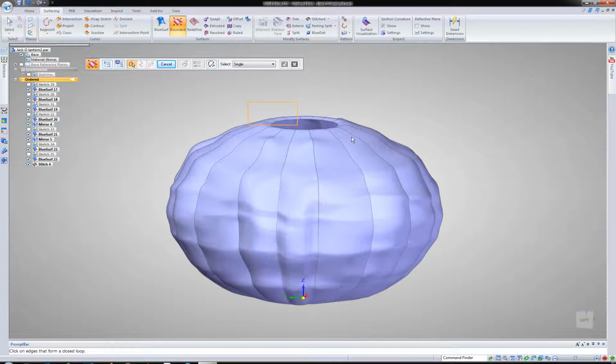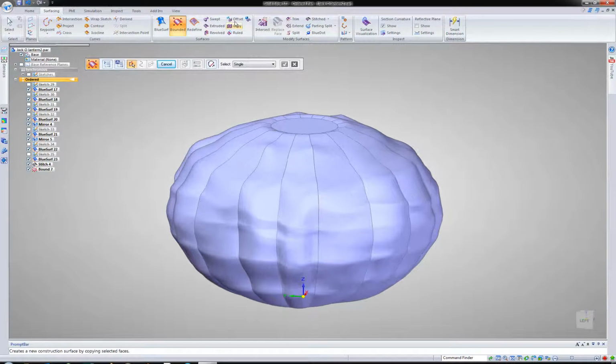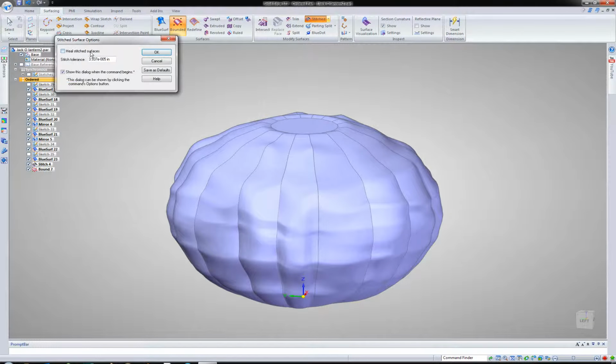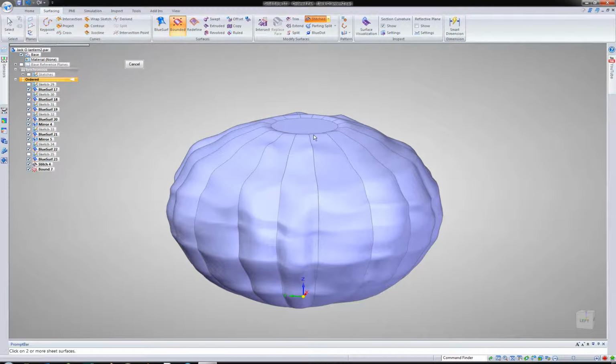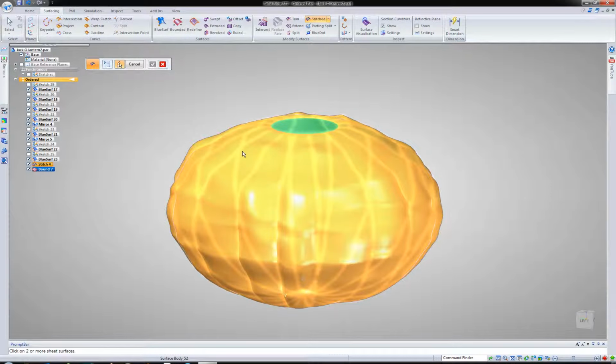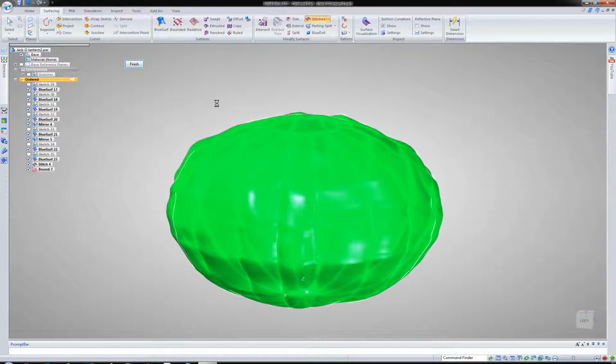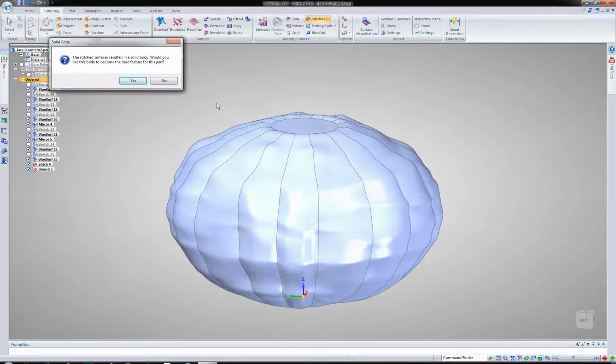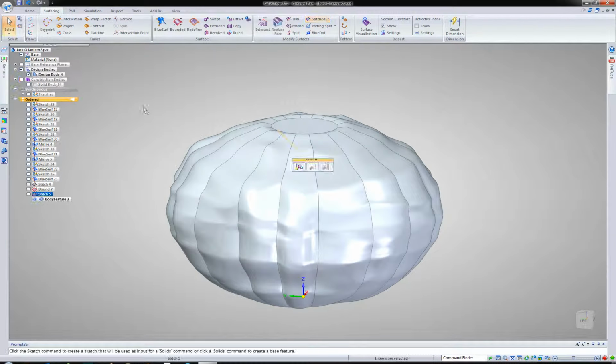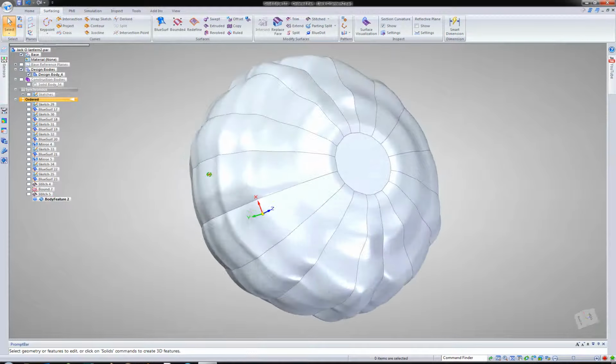So just a quick, simple window to grab all those edges and go ahead and make a cap geometry using bounded edge. And once that's done, we're going to come over here and stitch it again, but this time we're going to do a healing stitch. So in this case we have this surface and of course the design body, and since it's capped off now, it kind of understands, hey, once you do this, you want to go ahead and make it a solid, and yeah, this is the situation. We want to make this a solid.